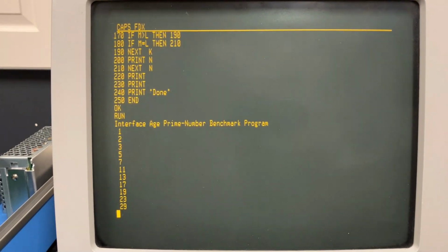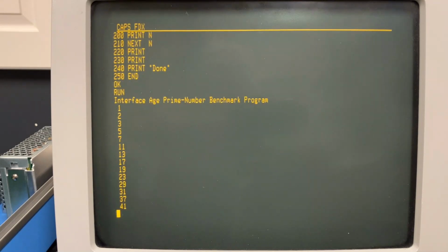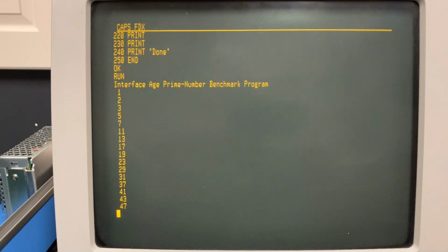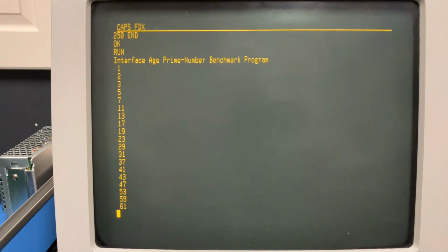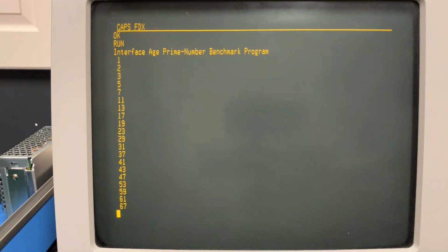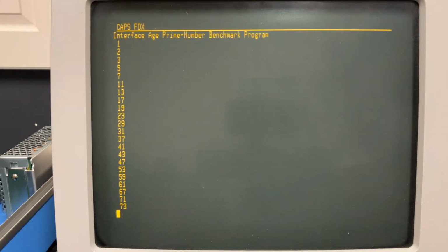All right, so we have got a console serial port here using the 2 SIO equivalent that we made here on the interfacer board. We have the cassette interface on that same board, so kind of 2 for 1, that's nice. And we've demonstrated several other boards in addition to the solid state music that we can use to make a drop-in equivalent of the Altair Cassette Interface.